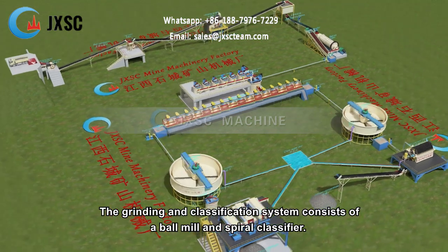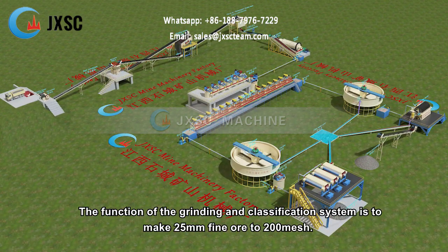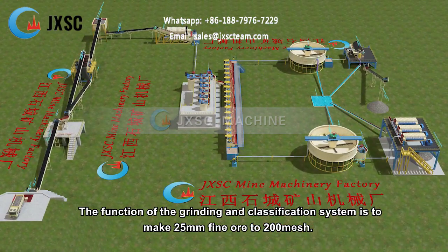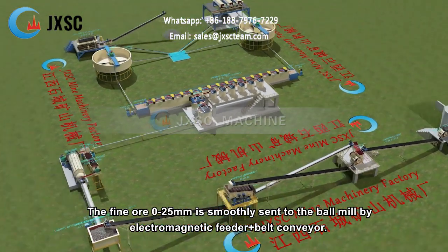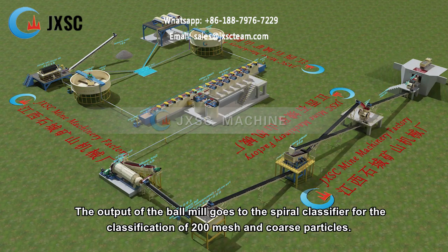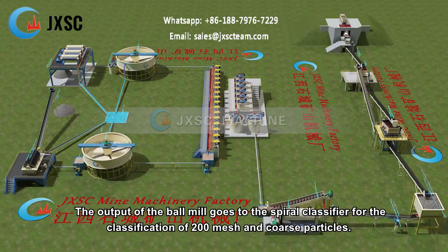2. Grinding and classification system. The grinding and classification system consists of a ball mill and spiral classifier. The function of the grinding and classification system is to make 25 mm fine ore to 200 mesh. The fine ore 0 to 25 mm is smoothly sent to the ball mill by electromagnetic feeder plus belt conveyor. The output of the ball mill goes to the spiral classifier for the classification of 200 mesh and coarse particles.